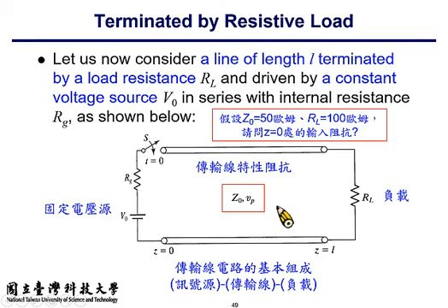Well, it depends. If the internal resistance of the generator, I mean RG, does not equal 50 ohm, you will have another mismatch at the left end, right? Then you will produce another signal, which in this textbook is labeled as V minus plus.